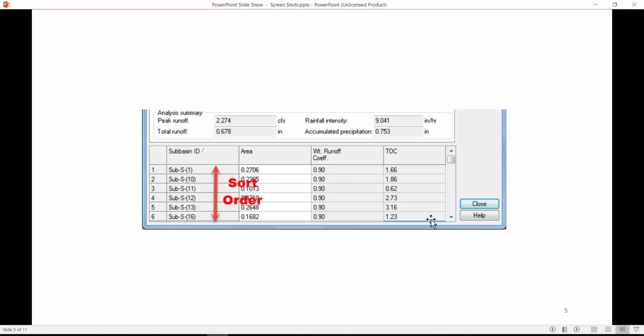Multiple network element dialog boxes can be displayed if desired. However, the computer monitor may become somewhat cluttered with multiple dialog boxes. If you have dual monitors at your computer, you can grab the element dialog boxes and drag them to the other monitor, allowing you to more effectively edit the network. Once completed with the data input for a particular network element, click the Close button.